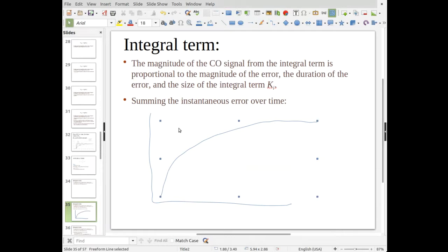So the original system may have been pretty fast, but then when we get to the integrator piece here, it slows it down. Now what's interesting is once you put that proportional in there, sometimes you'll see a hump like this. The proportional or derivative control gives you this little hump over here. But then you can see the integrator starts driving that error over. And like I said, I'll try to do a better plot of these and get it uploaded for you.